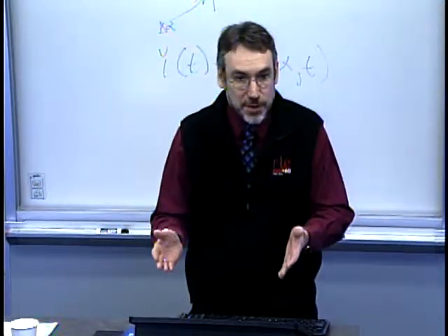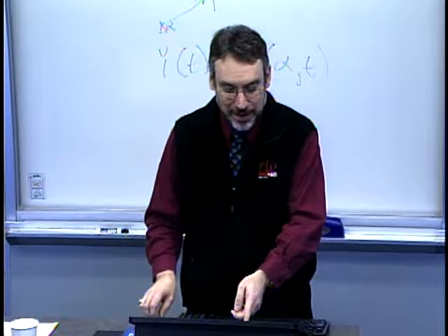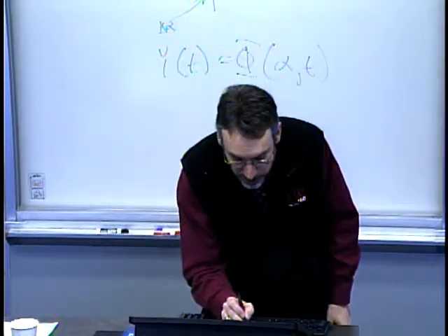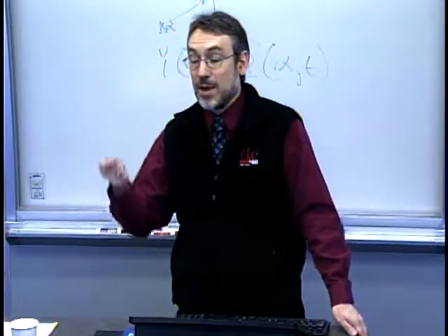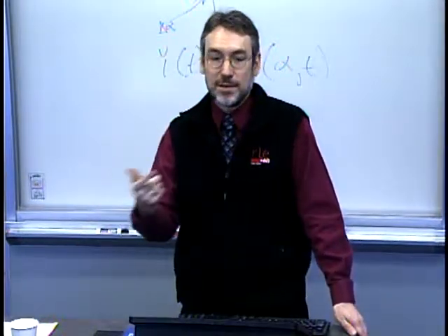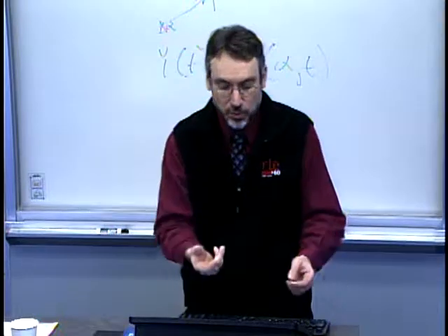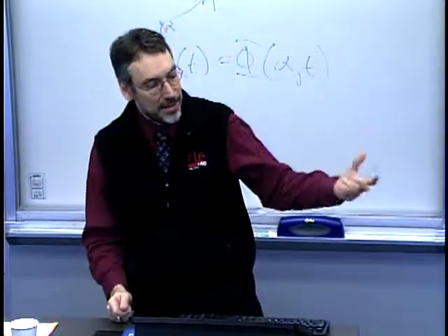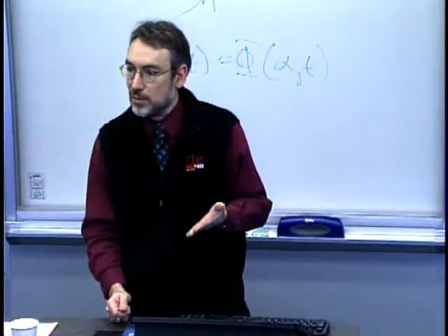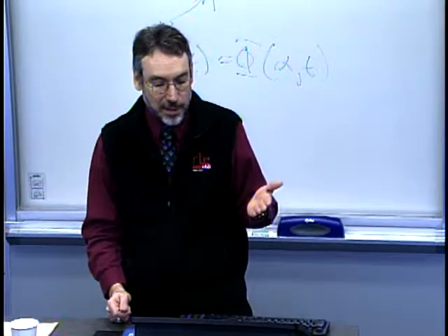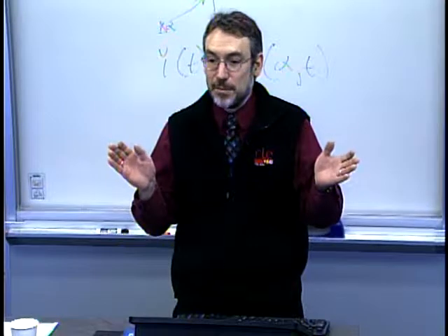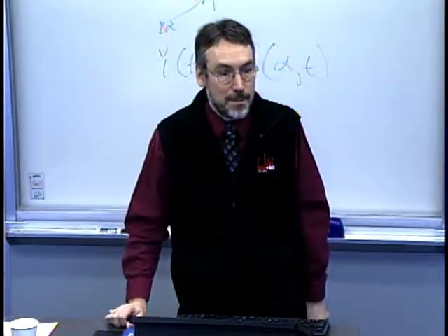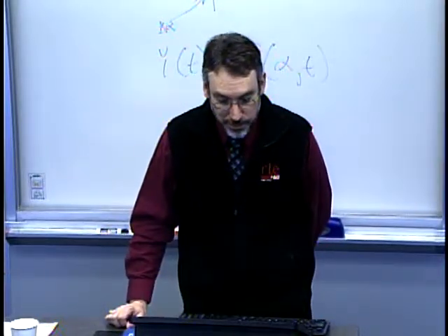Something got misadjusted on the tool. I need to readjust it and get it back in, because maybe there's even a little bit of something going on there. Or it might have been a single event that didn't require adjustment. Maybe you go in, you investigate, and you find that one piece of source material coming in, that piece of metal, was much thicker than it was intended to be. Almost like a piece of steel 0.3 mixed in with your steel 0.6.